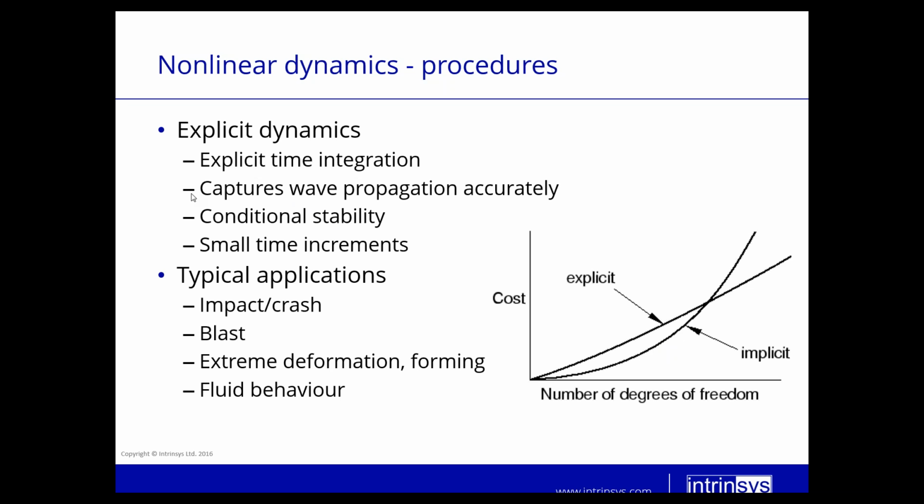This procedure can capture all the wave propagation in the structure. However, it's only conditionally stable. That means it must take small time increments. We'll take a look at this one in more detail. And although it has to take a lot of small time increments, one increment is much more cost effective than an implicit analysis. So as you see on this graph, an implicit analysis for low number of degrees of freedom